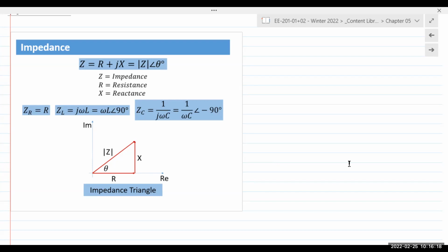Resistance is a term that you're familiar with. When you have electrons passing through a piece of material that allows the conduction of that electron, hence a conductor, any opposition to the passage of that electron is termed as resistance. So it is direct opposition. That direct opposition is termed as resistance. Reactance, I like to call indirect opposition, meaning it allows the passage of current without any problem, but the moment you start to change the value of that current, it starts to oppose. And that is termed as reactance.